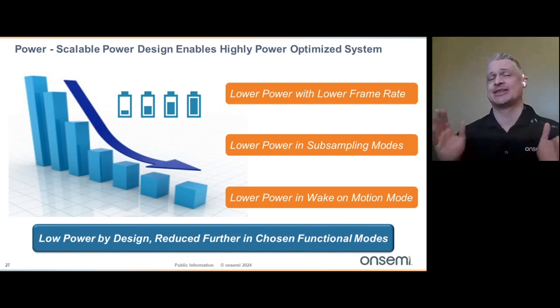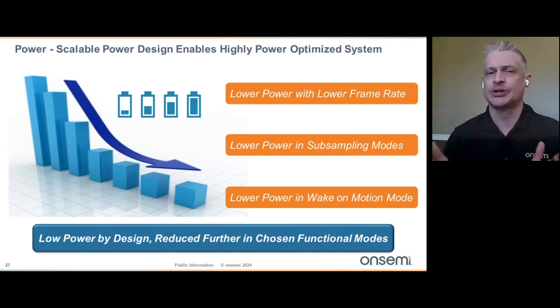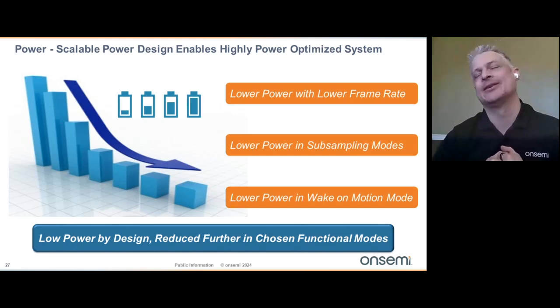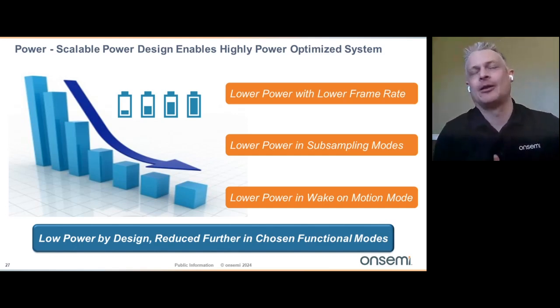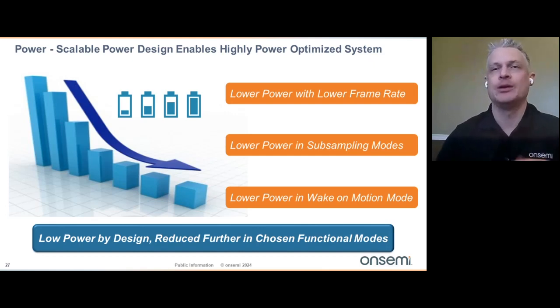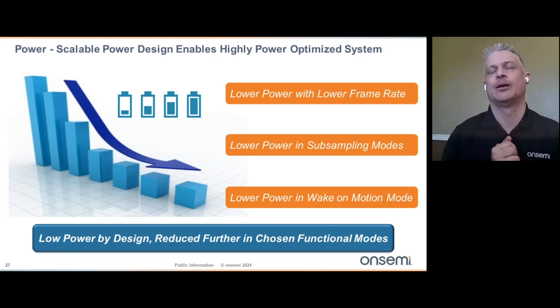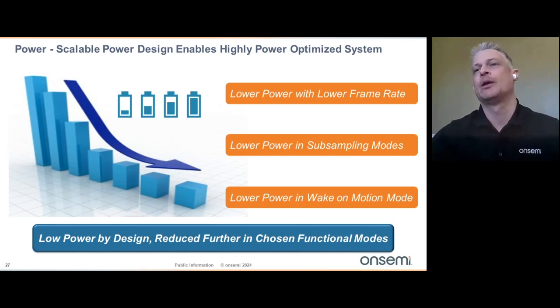But if you've got a sensor that's sitting there running 100% of the time, you'd like to put it into a very low power mode that is going to draw the least amount of power. And you can turn off elements within the sensor that don't necessarily need to be on when they're not being used. We've developed some mechanisms around that ourselves. But I think this is one of the trends for improvement in the industry: getting power that truly scales with the actual resolution and the frame rate and doesn't saturate at some point.